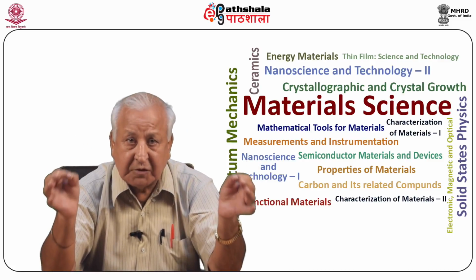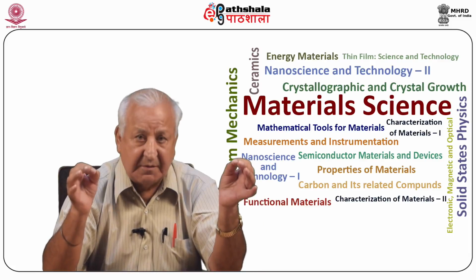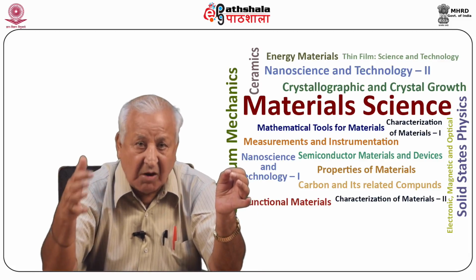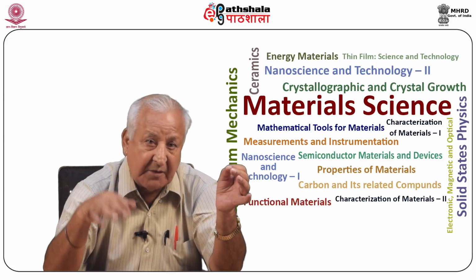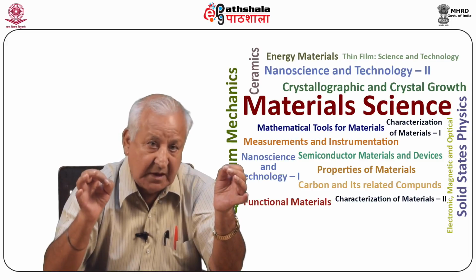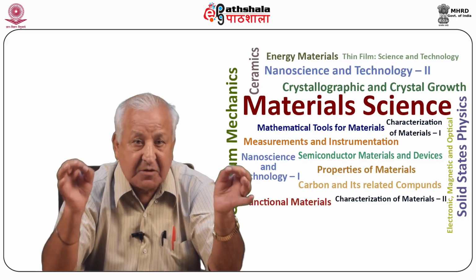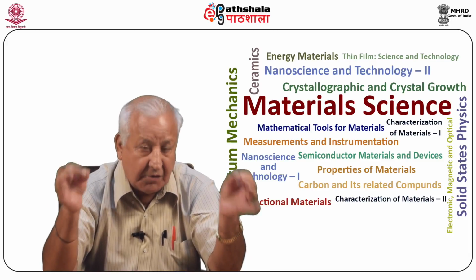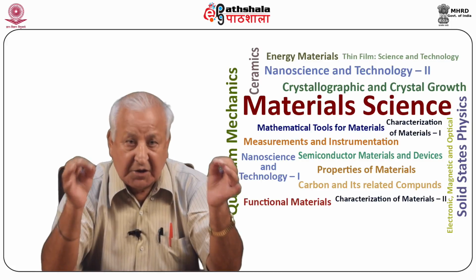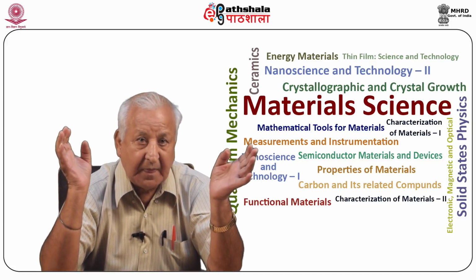To favor growth of crystals on the bottom rather than at the surface of the melt, the top of the crucible is kept 10 degrees centigrade hotter as compared to the temperature of the bottom by adjusting power of the heater. It has to be ensured that the temperature is kept constant, since a sudden drop would cause the production of small crystals rather than the dissolved few large ones.